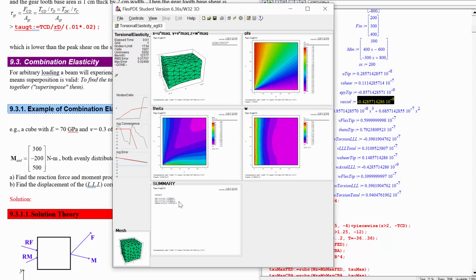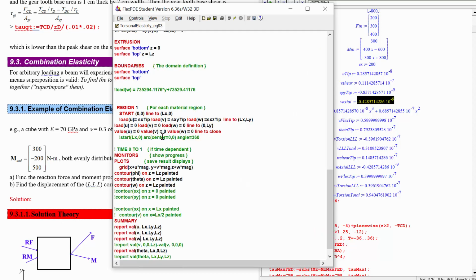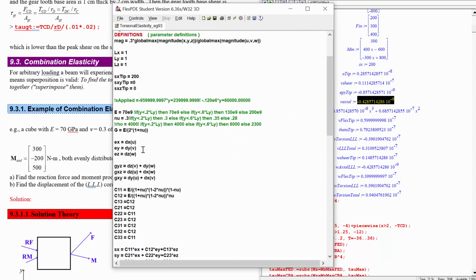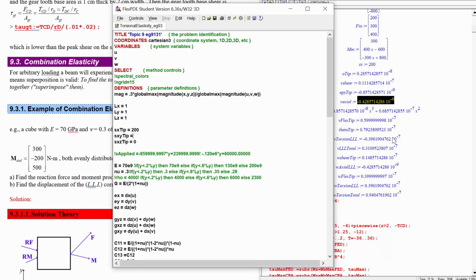The next easiest stresses to build in are the shear stresses that produce these net forces. Again, because the area is just 1, those ones we can find out by putting the stress in the Y as what we would want in the Y direction, 300, and the stress in the Z as what we would want in the Z direction, 400.